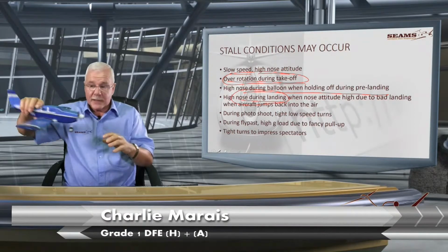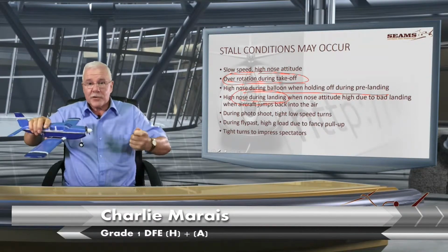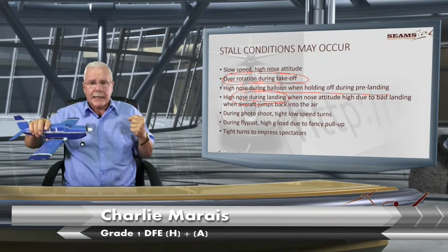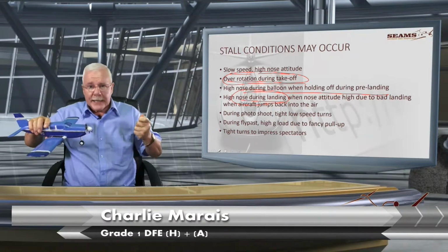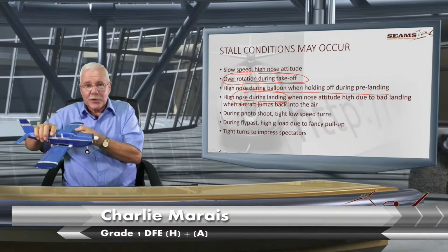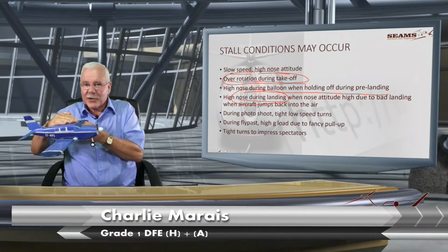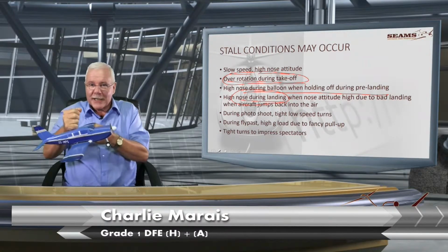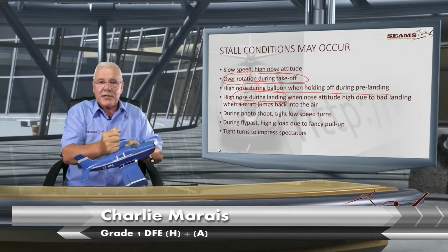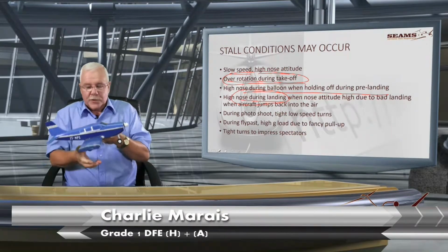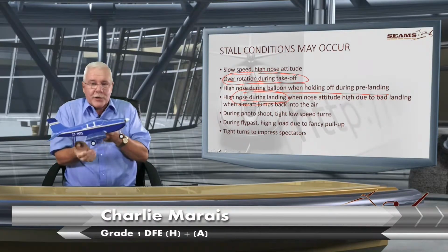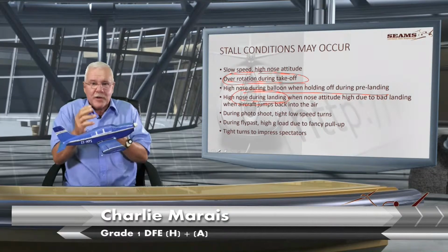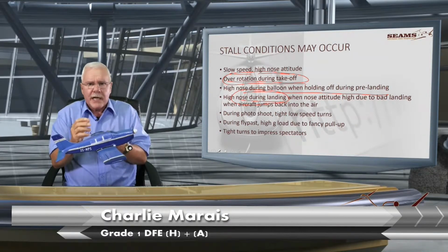From the moment you've rounded out and you've closed your throttle, don't yank it closed, slowly, and as you close it, you catch it because she wants to go and settle in. Say, and you hold her slightly back, and there she settles in. In other words, not on the nose wheel. Nose wheel landing's bad. It's normally when you're too fast and too high. Go around. Can do it again.